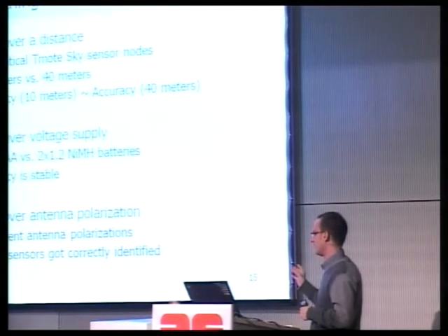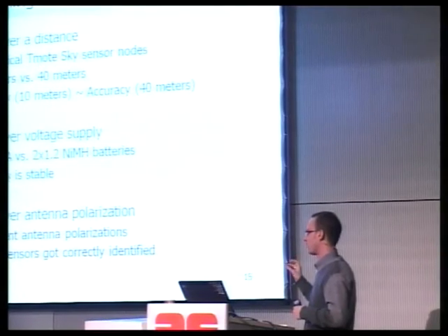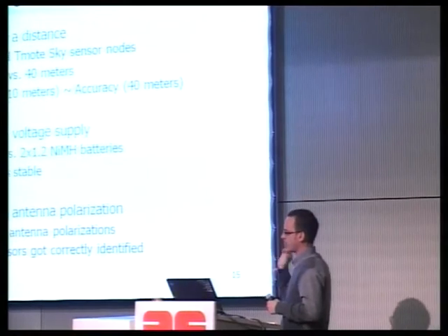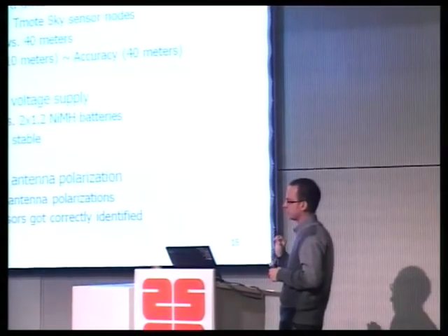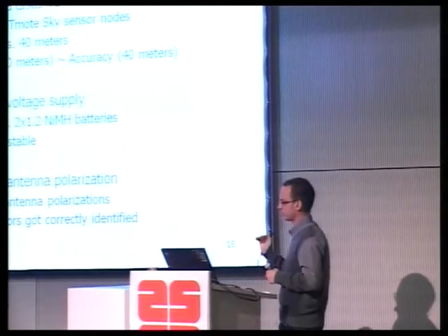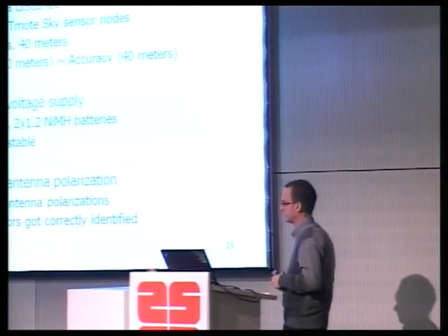This is kind of not a problem given the fact that these are low-power devices. What we didn't test is that these were all regular transmissions. We did not test if the device transmits very intensively for some amount of time and then it stops. This we did not experiment with in this setting. We just used regular transmissions, 500 milliseconds per packet for 1 hour. We could see some deviations at some moments, but they were not influencing the accuracy that much, plus or minus 1 or 2%.